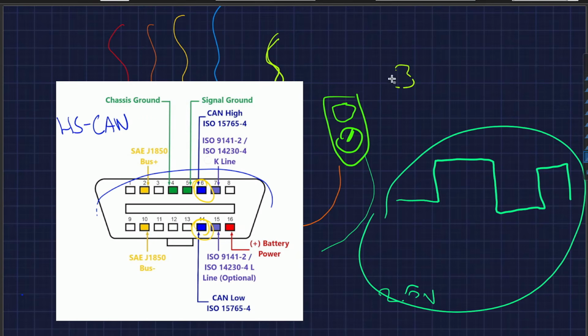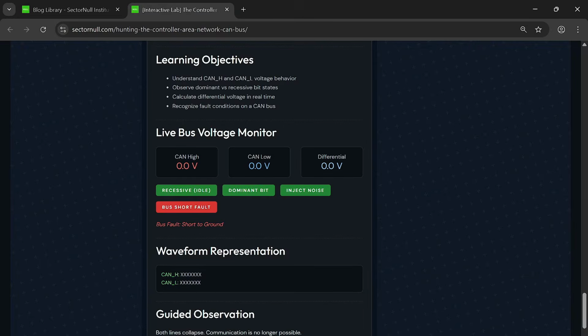Now, when they enter limp mode at the transmission control unit, there's a good chance that you will just be stuck in third gear. So there will be no upshifts or downshifts. It will just stay in third gear, and the maximum speed, of course, will be limited. That's basically what happens when something internally in the transmission fails, or the communication between the transmission and engine control unit fails. And yeah, this will happen in most vehicles. In the best case, with third gear, you can at least still get to some mechanic or go to your home. But most of the time, the vehicle just stops and it will refuse to go anywhere.